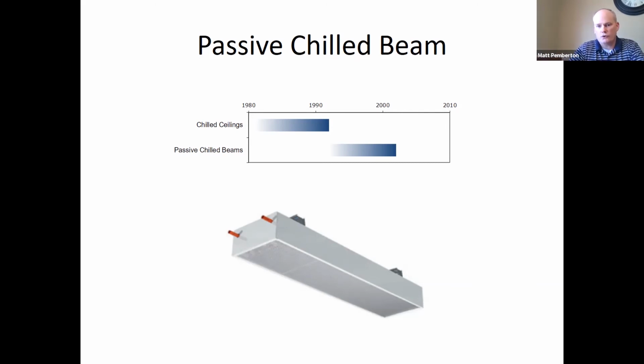So we're above space dew point, we're a dry coil, and that's the difference. We don't need filtration on a dry coil, but if you followed every word of ASHRAE, you would need filtration on wet coils. And so that's the difference between a wet and a dry coil. A sensible-only application is really what we do with all of our overhead ceiling style chilled beams.